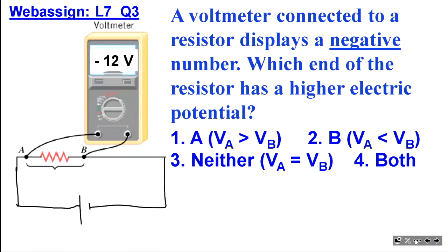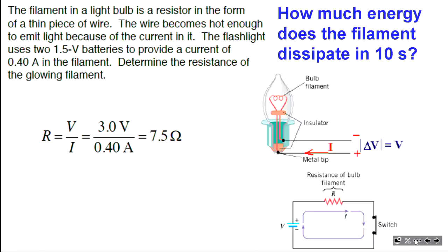Well, in this situation, this is plus, this is high, so this electrode represents the red, and this the black. So the black, the one which is supposed to measure lower potential, is connected to a place with a higher potential. Well, we have solved this problem.